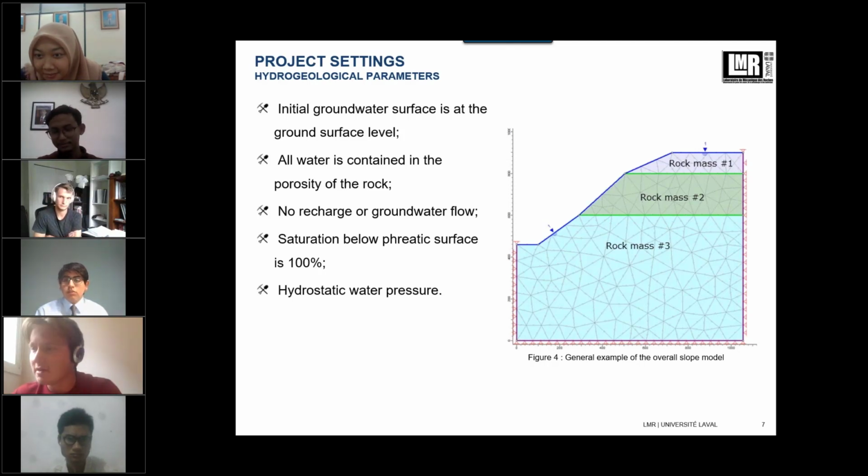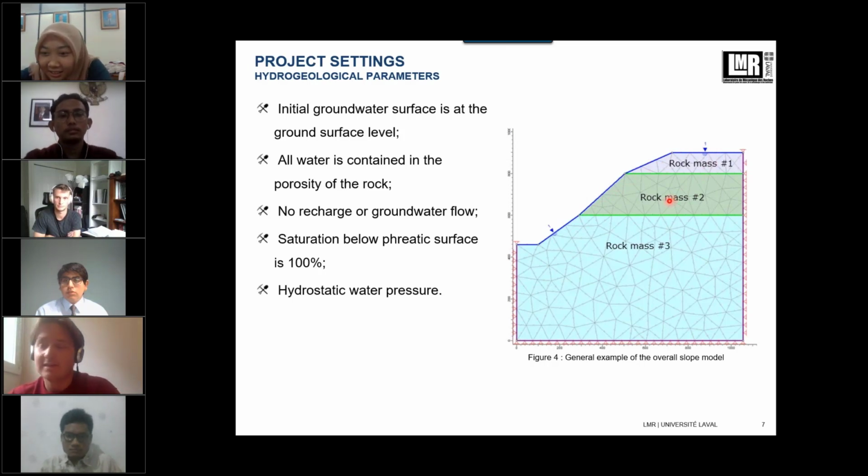With all this information, because there is no precise way to input a pumped water table, and because there was no information about pumping wells or drains, and for conservative reasons, the team decided to design the pit with a fully saturated slope, meaning that the phreatic surface will follow the topography, as you can see with the blue line here. In reality, this will not be the case because of evidently pumping wells and drains.